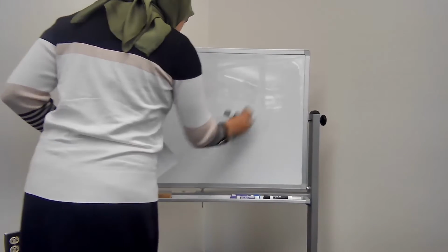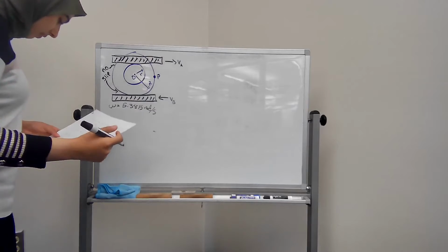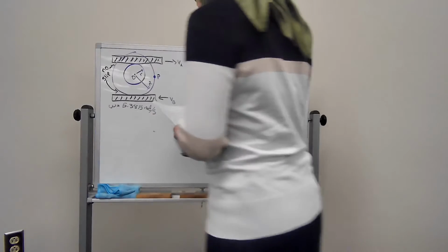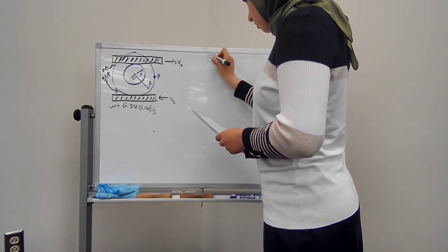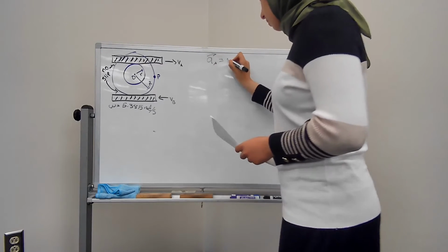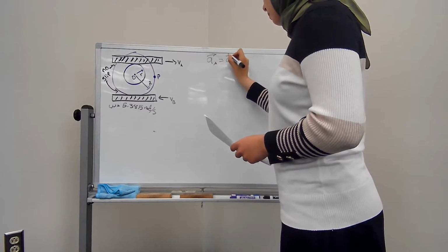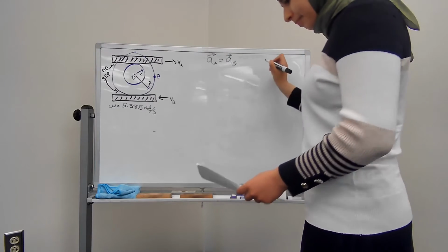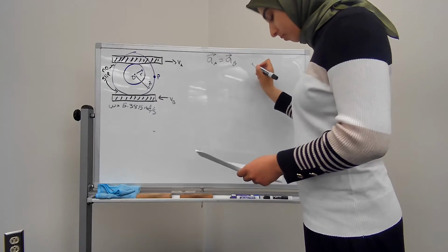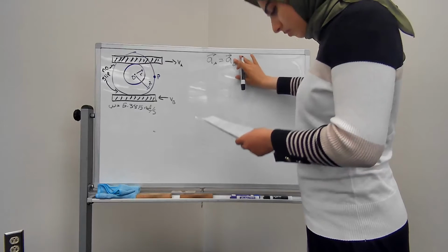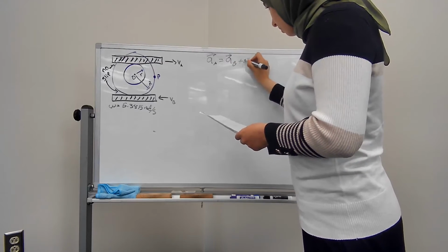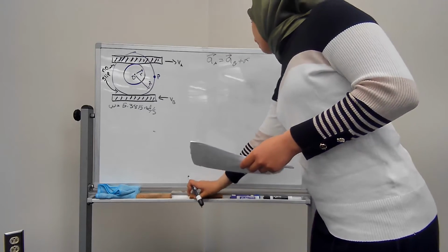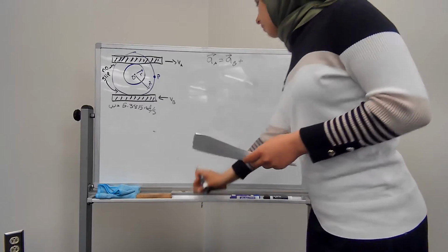The next step in this problem is to find an equation or a numeric solution to alpha. And we can get this by using the acceleration equation that we've been using so far in chapter 2A. That equation is the acceleration at A is equal to the acceleration at B plus alpha cross R of A slash B minus omega squared times R of A slash B.